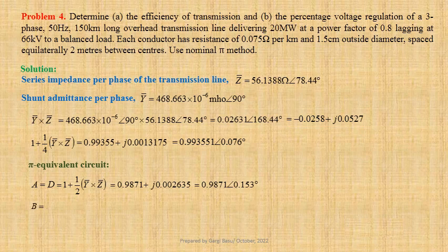B equals Z, that is equal to 56.1388 ohm ∠78.44°, and C equals Y times (1 plus 1/4 of YZ).